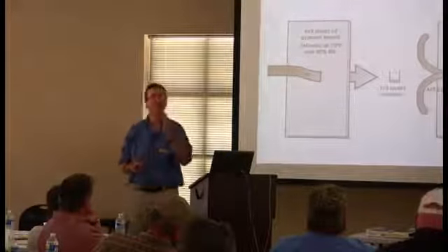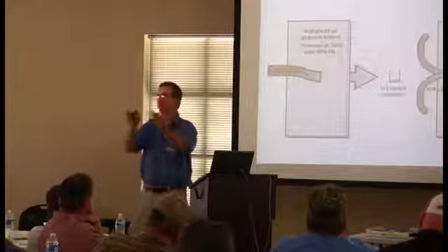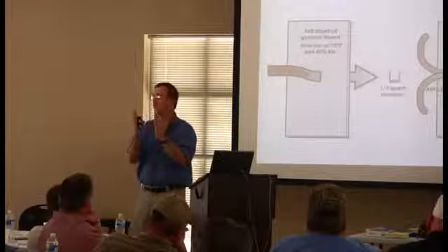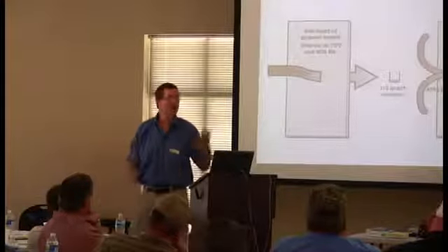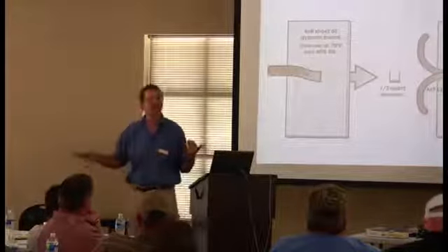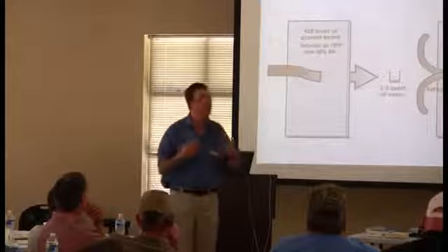In fact, it was really a problem in houses where they put synthetic stucco on the outside and they put plastic polyethylene on the inside, because then we did really create two vapor retarders and trap moisture. So the bottom line is, and you're going to see this in the energy code, there is no requirement for any kind of a vapor retarder on your insulation in walls or ceilings.